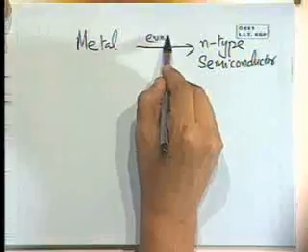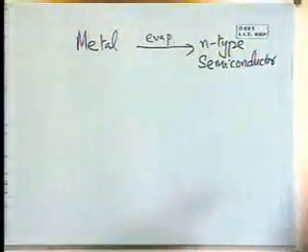That's the meaning of the word to rectify, as used in this context. Rectify generally means to fix, but in this case it means it allows in one direction and not in the other. So we'll see why it does that. And an ohmic contact, as I said, the characteristics are linear, which implies that it allows it in both ways. You're correct. So we've got some kind of an evaporation of a metal onto an n-type semiconductor.